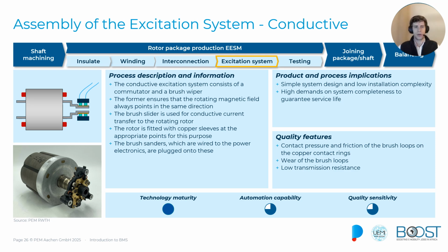This step involves securing brush holders around the rotor, inserting brushes to contact the commutator or slip rings, attaching springs for consistent pressure, and ensuring all components are firmly fastened. This once again comes with the disadvantage of wear due to the direct electrical contact of the parts.